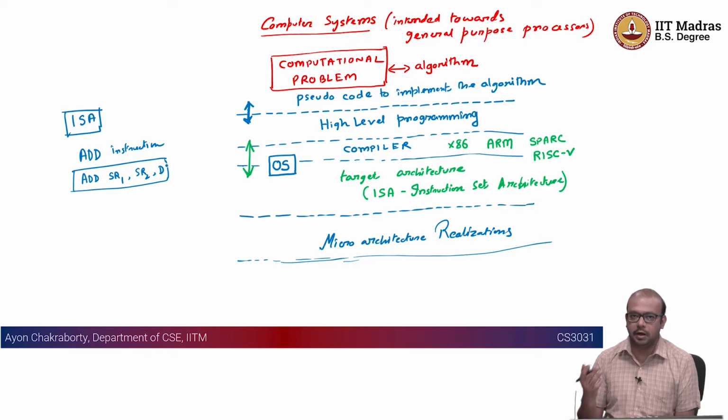If you just recall, from the least significant bit, you have to propagate the carry to the next stage, and at every stage the carry propagates, it is going to introduce delays in executing the addition. The gate delays are going to add up from the least significant bit to the most significant bit, or the carry out. So, you can use a faster implementation, but that implementation detail is concealed by the microarchitecture, that is not exposed.